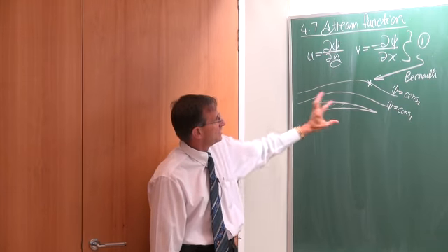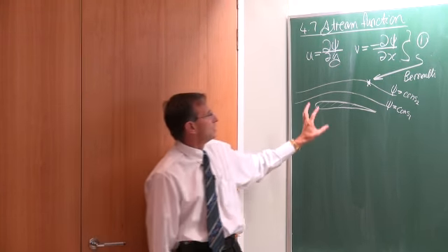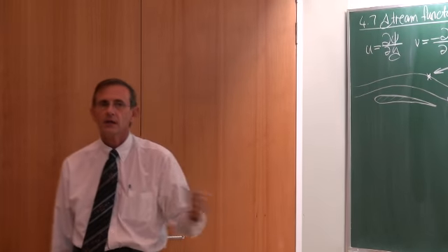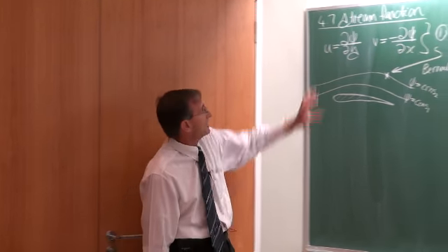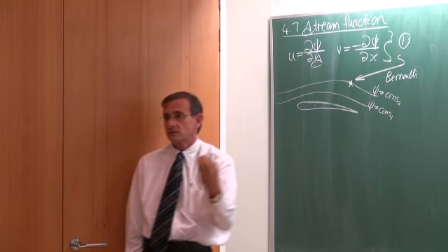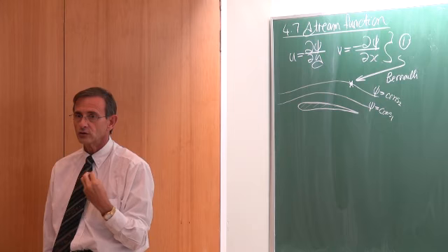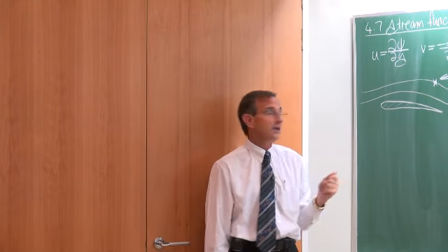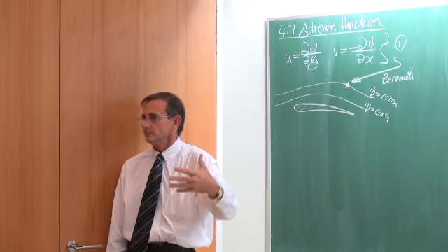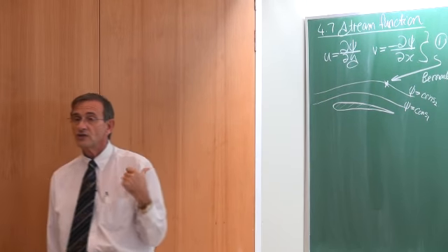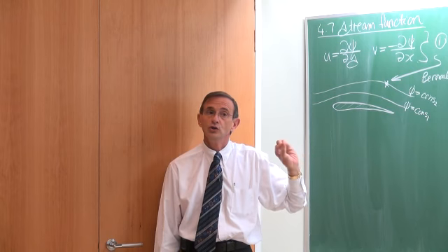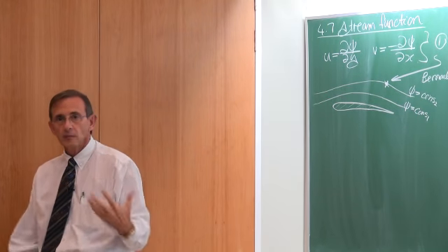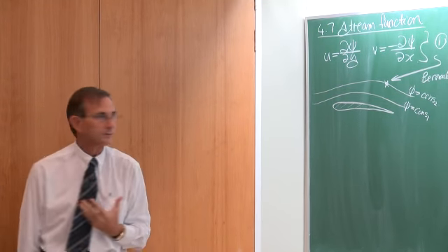The result of that is that with these streamlines, it was possible for people to actually estimate the lift on bodies, like aeroplane wings. The disadvantage, unfortunately, was that in this approach, to get this mathematics so that we can get solutions out of it, it was necessary to assume that the viscosity is zero, which means that the shear stresses on the wall would also be zero. So the disadvantage of this method was that it wasn't possible to determine the drag on aerofoils or bodies. But that has been complemented with lots of wind tunnel work.